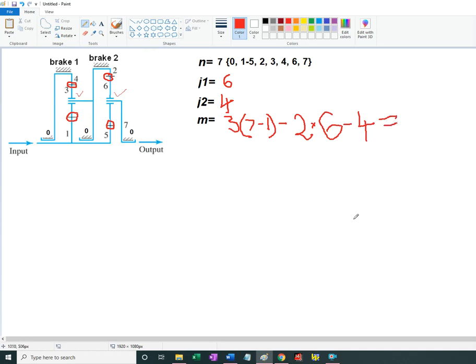The expectation is that the number of degrees of freedom is 2, because by engaging one or the other of the brakes, I'm suppressing a degree of freedom. I'm left with 1 degree of freedom, which will be the motion corresponding to 1 input and 1 output. So we have 3 times 6, that is 18, negative 12, negative 4, and it's indeed 2 as we were anticipating.